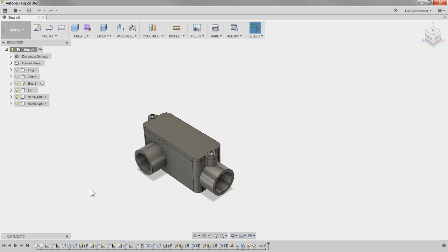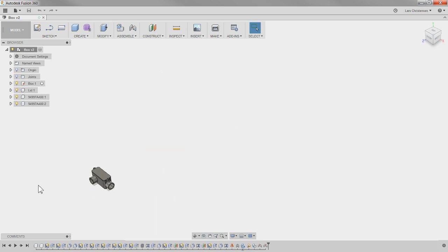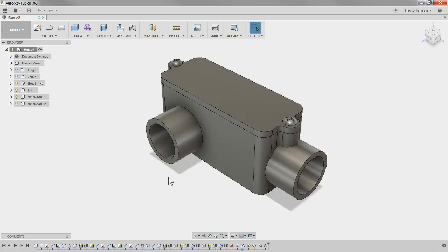So if you're a brand new user, you're now spinning, suddenly the model is over here and you're trying to find it and you're scrolling and it gets off the screen. Double click your middle mouse button and it will bring it right back to where you were. You can also hit the F6 on your keyboard if you want to. So locate F6 and that will do the same thing.